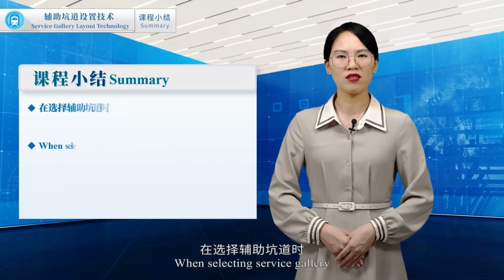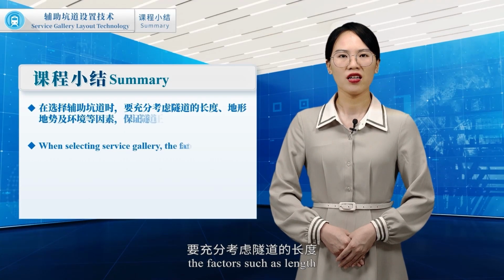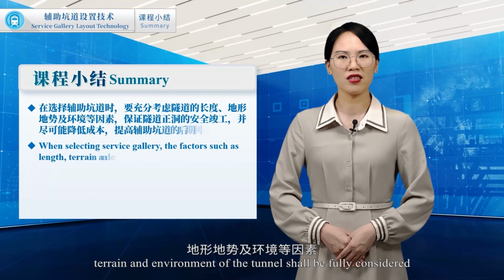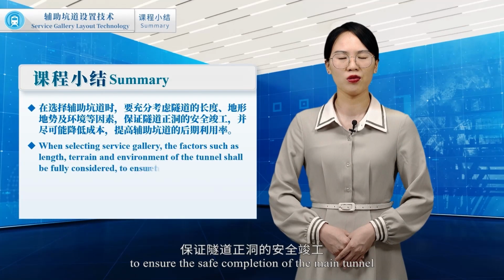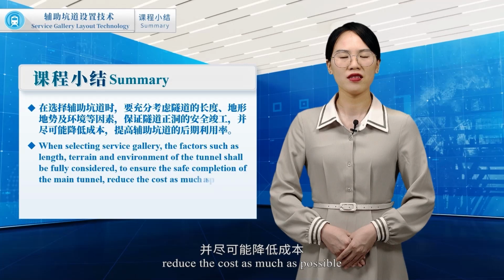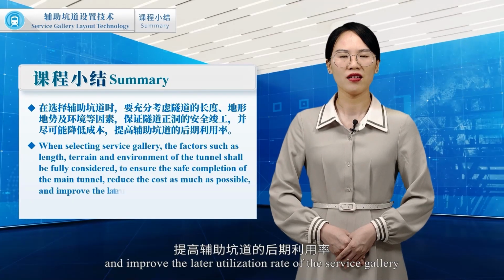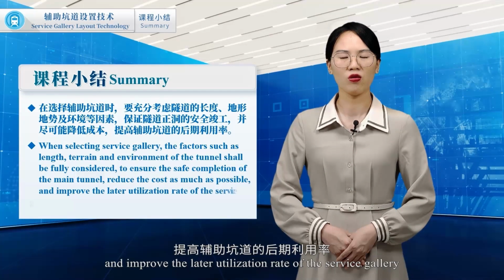When selecting service gallery, the factors such as length, terrain and environment of the tunnel shall be fully considered to ensure the safe completion of the main tunnel, reduce the cost as much as possible, and improve the later utilization rate of the service gallery.